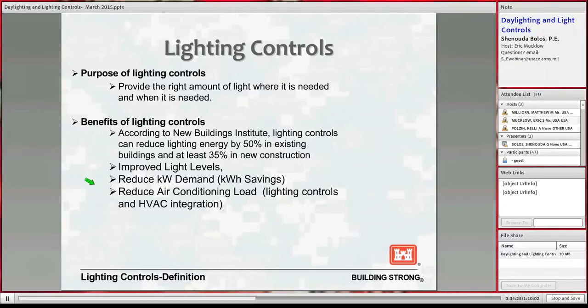You could have a more intelligent system. You can have a lighting control system integrated with the HVAC system. You can have an occupancy sensor when you enter any room, any office room. You can turn on the light and increase the air conditioning running. You could run the air conditioner at a minimum, probably 10 or 20%.